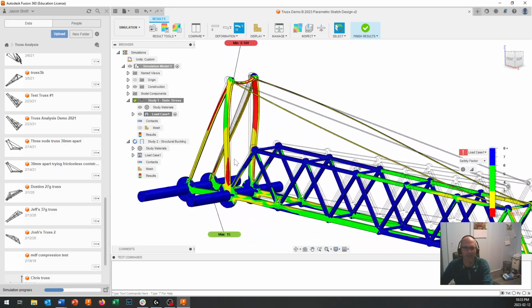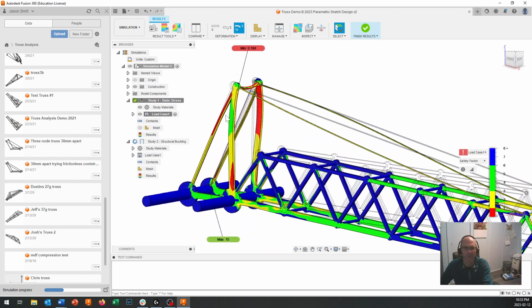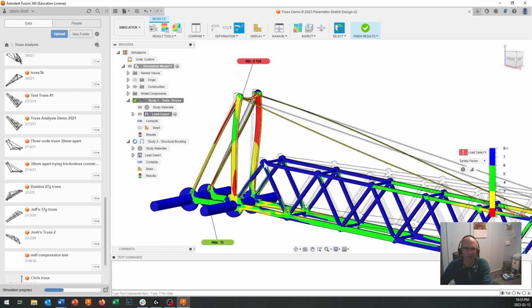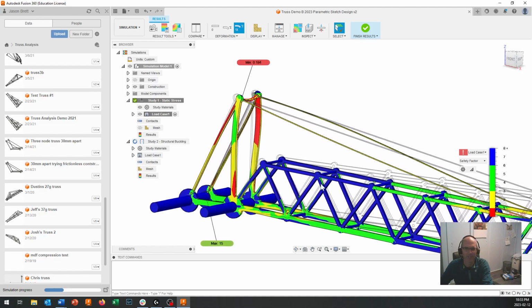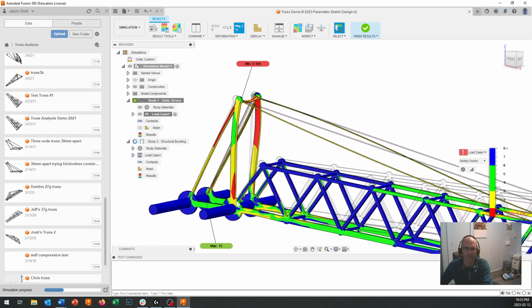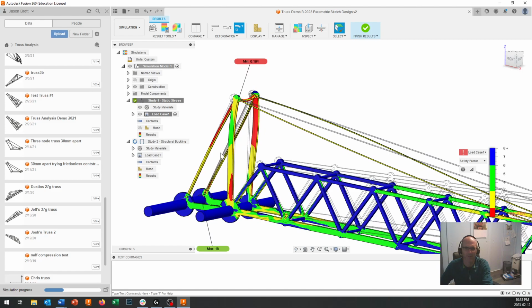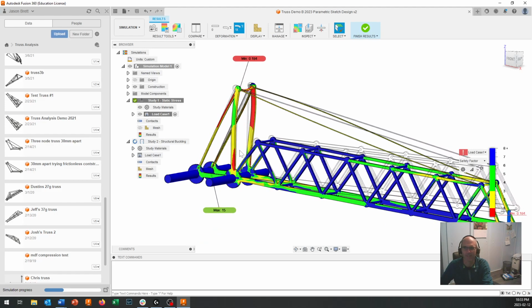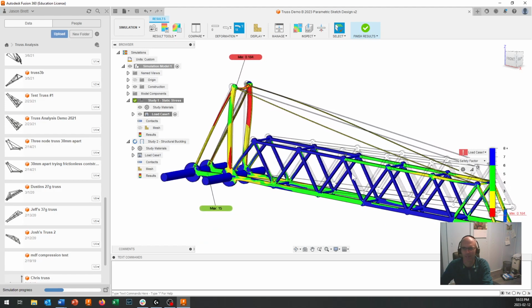And I knew going in that these long members up here were going to be bad news. But I was kind of constrained because of where that node is. I might have to change this up at the back so that this comes down right in here and I get rid of that node. Then I can put two nodes going up there to stiffen it up. We'll see what the structural buckling analysis says right on there when it's all done.